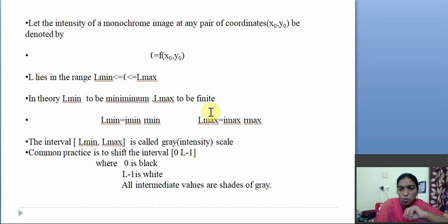In between, there are so many values in the image. That means the range of this particular image is 10 to 150. How can you allocate the number of bits to that particular image? It is difficult in such a case. That's why we take some uniform values. In common practice, 10 is taken as 0 and 150 as the higher value; I just normalize these values.